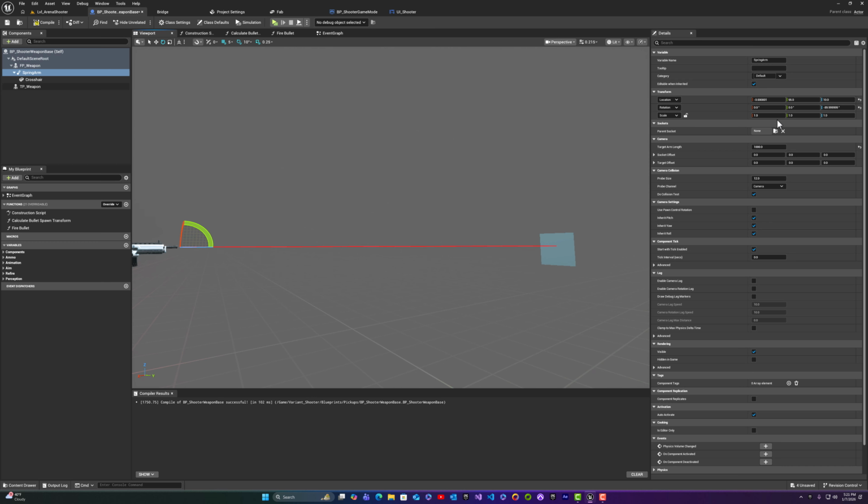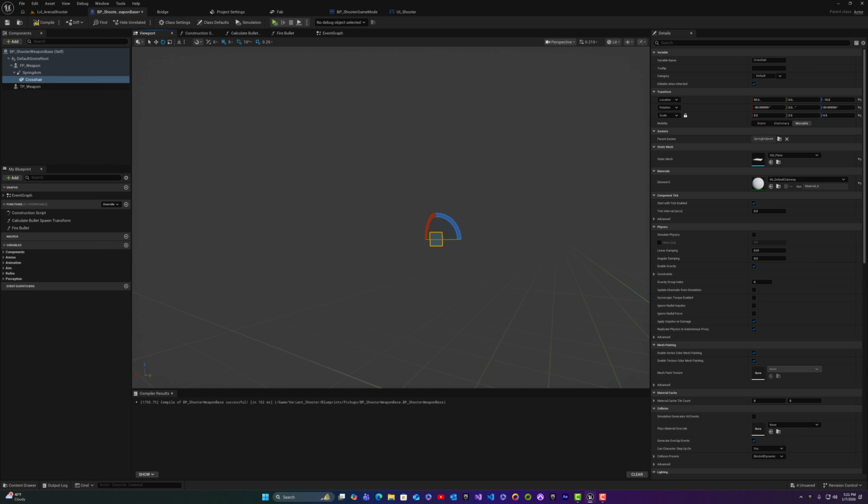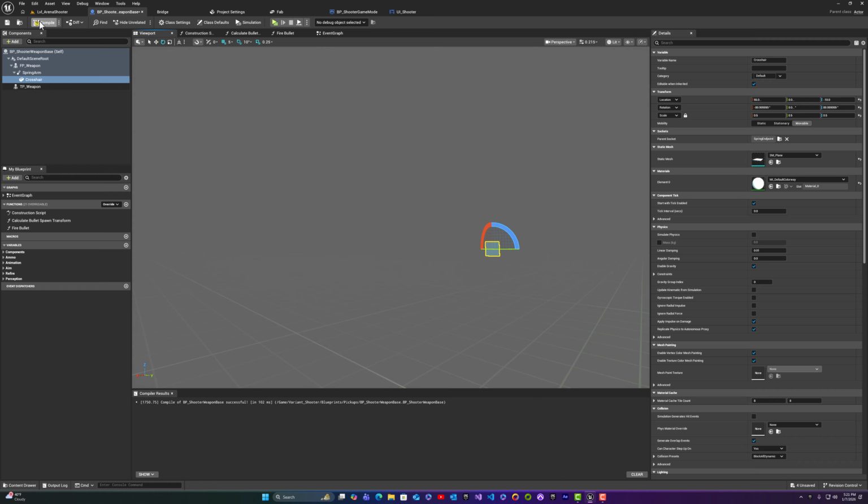And it's pretty common that I will also make this smaller, that is to say the mesh, on every axis. So I'm going to say maybe 0.25. 0.25. Of course, I could have padlocked that. 0.25. I'll padlock it now in case we have to make any further adjustments later. And maybe we'll start with all three at 0.5. Not 5, 0.5. Okay, and we'll see how it goes.